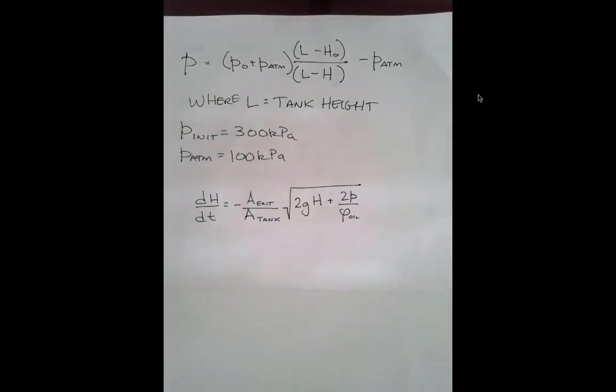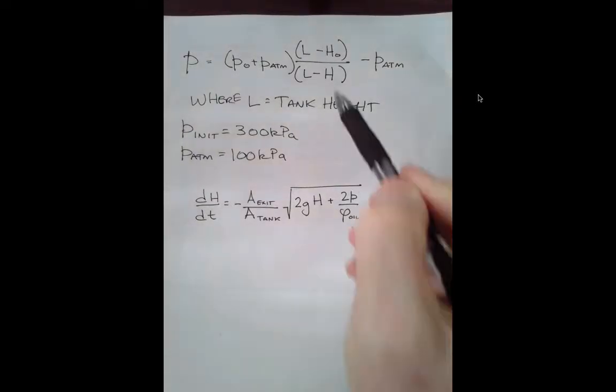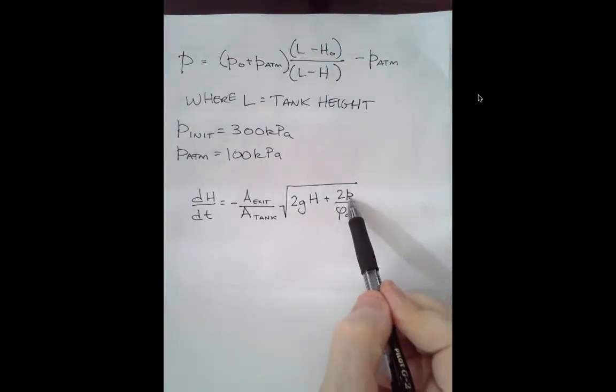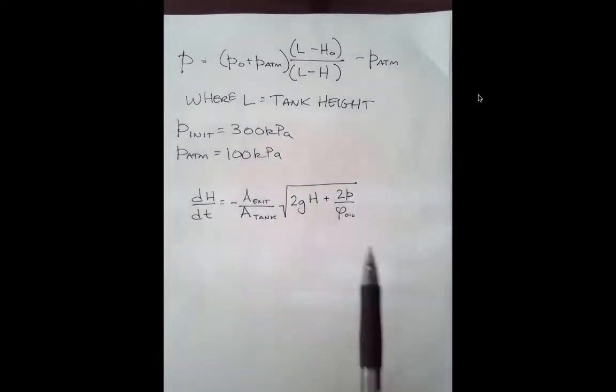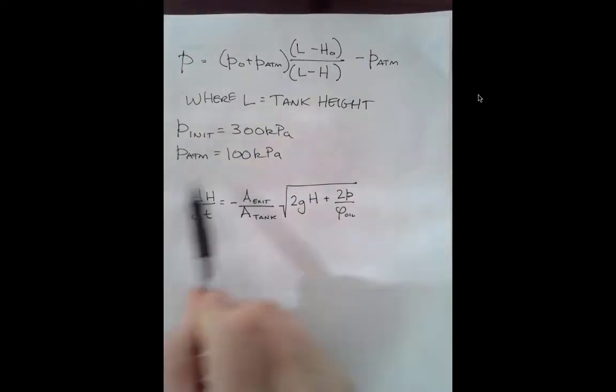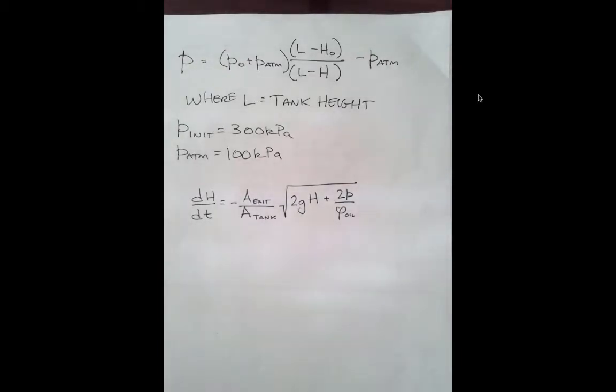Now, it's not going to take too much to figure out that pressure is a function of depth in the oil. So this P is not a constant. It changes as H changes. So finding an analytical solution to this is probably not impossible. Things that are in square root forms like that are findable. But now that we have another tool, we can just go ahead and do this numerically to predict oil depth at time. And let's just do it for 1 minute time intervals.